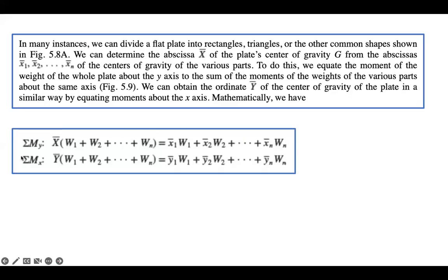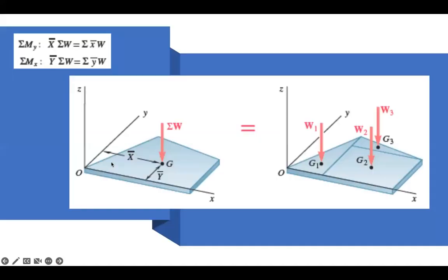Always remember that we use x bar with the sum of the moments about the y-axis, and y bar with the sum of the moments about the x-axis. Okay. So basically, here's how we apply the tables we saw previously, these tables over here.